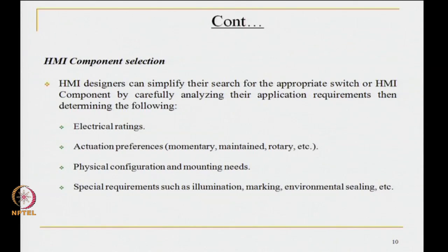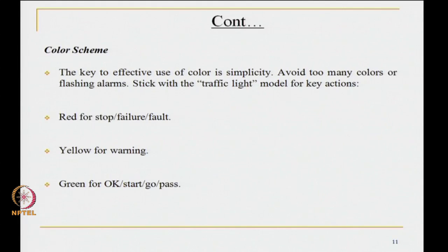Just as there are HMI component selections, so there is the issue of the color scheme, which is central to understanding the man machine interaction. The key to effective use of color is simplicity, like everywhere else. The purpose is to avoid too many colors or flashing alarms. Stick with the traffic light model for the key action. If you stick to the traffic light model for key action, what is it that you get?